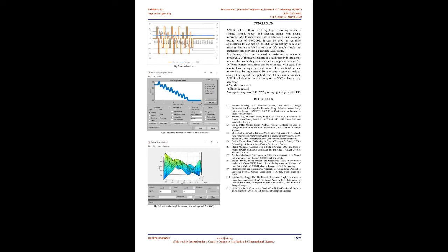In the fuzzy control system, fuzzy reasoning is a map of the input-output relationship. The neurons can map any functional relationships. It also can be used to make the fuzzy inference come true. Also, the neural network can realize fuzziness and non-fuzziness. Hence the neural network can represent all fuzzy control too. ANFIS is used to construct an input-output mapping based on the initial given fuzzy system and available input-output data pairs